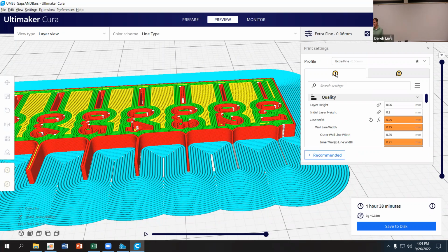And if you want to move to something like nylon, nylon has a very significant temperature deviation. It's also quite soft. And so it tends to get gummed up in the mechanism itself, and it has a higher melting temperature. So you have a higher temperature on the hot end, larger temperature gradients, more contraction, as well as a squishier material, which means that between where you're applying force to the filament to where it's being extruded, there's going to be more deformation inside that component, right? And so that makes it a little bit more difficult to print.